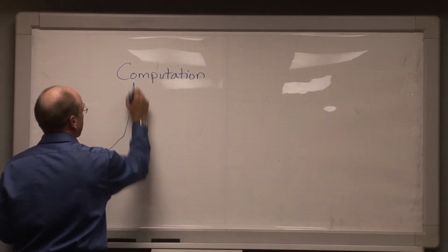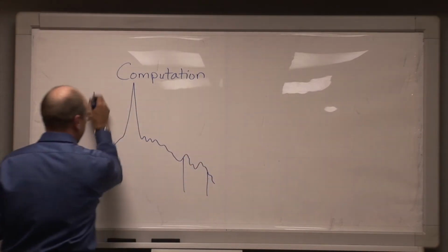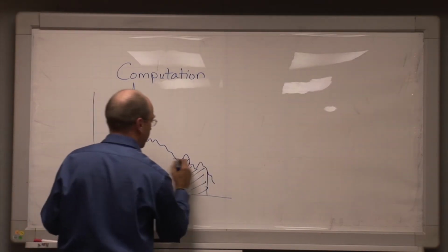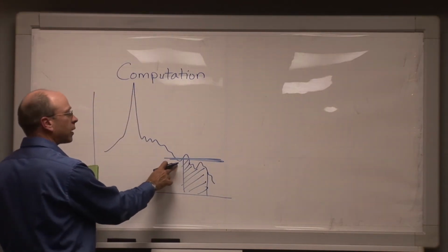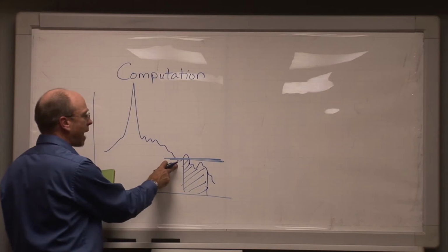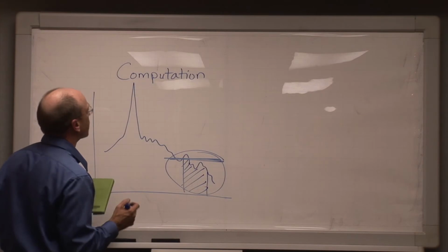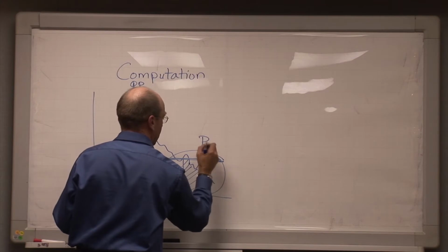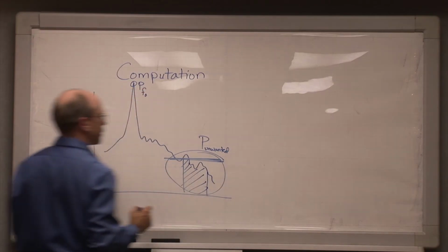We look at the transmitted spectrum with its funny little area out here that we measured where the interference was occurring. We know how far we were from this transmitter when we made our measurement. We can correct that to get the power level that should be in this part of the spectrum at any given location away from this transmitter. We also know how much power was up here at its fundamental frequency. So here's the power in the unwanted emissions down here.